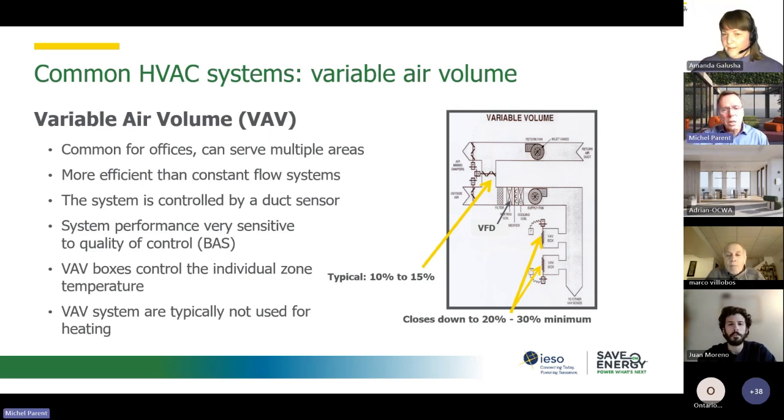So that's another piece of information you need to identify. I did not show you a hydronic cooling and hydronic heating system, but just, let's say, off the cuff here, you need to also obviously identify, do I have a primary, secondary cooling loop if you've got chilled water? Do you have a primary, secondary heating system, which is very common? Is it a three-way valve, a four-way valve? And what type of boiler do I have? Do I have a condensing or non-condensing?